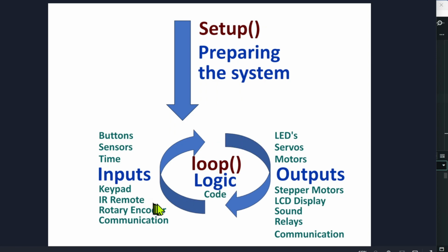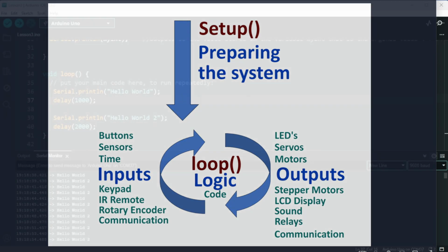But what it means is that during that delay period, no other item can receive an output and you cannot receive any inputs. This is why you see beginners struggling so much. One of the classic things, when I see someone crying for help, you look down their code and you go, oh my goodness, it's full of delays. So on this course, we're not going to learn about using delay. We're going to use a much better way to time our programs.